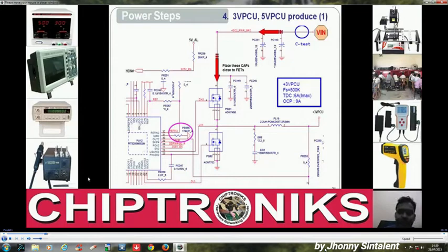Okay, there are two external MOSFETs. We call them synchronous switches. This is the terminology of electronics, synchronous, right? So these MOSFETs are also called synchronous switches, and Vin is connected to the top of this N channel MOSFET. So you see the arrow inside, N channel. In an N channel, current flows from drain to source, right? Drain to source.